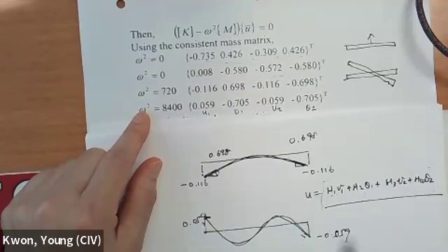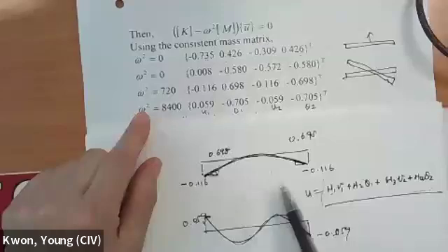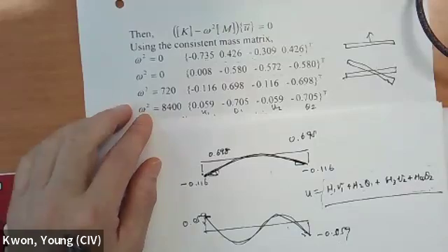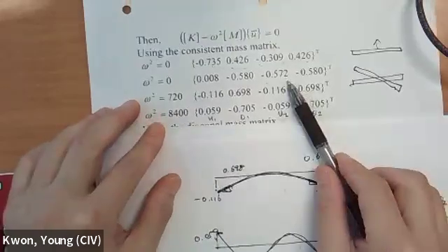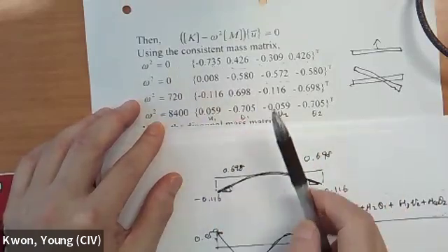But in our case, from our common sense, the first mode, second mode is going to be two waves, and the third mode is going to be another one, so we are using that information. More precisely, you plug into here, then you'll get this one. So we are not just cooking up any story, it is based on the shape function. So two non-zero frequencies and two mode shapes, and two zero frequencies with that one.